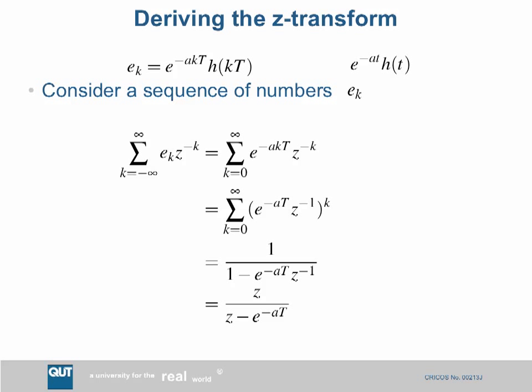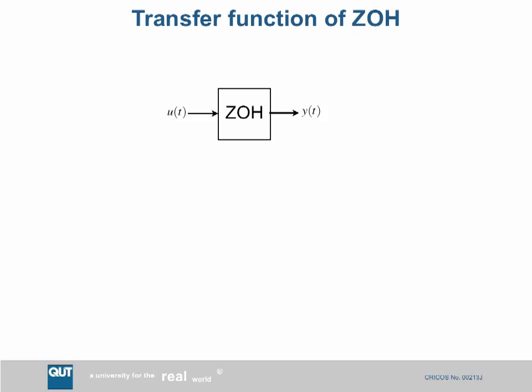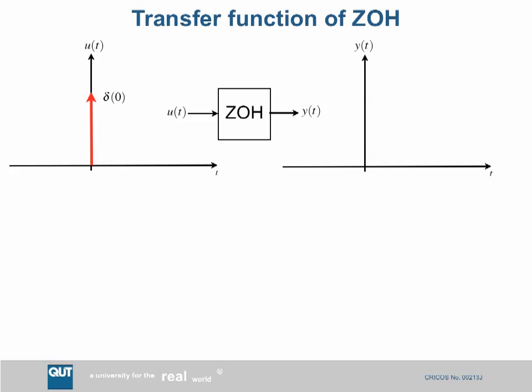So we've talked before about what a Z transform is. So here's a zero-order hold. And so what goes into the zero-order hold is an impulse, right? So if we put an impulse in at time equals 0, what comes out of the zero-order hold is a pulse, right? 1 time step wide. That's what a zero-order hold does. Converts a spike, a pulse, into a finite width pulse.